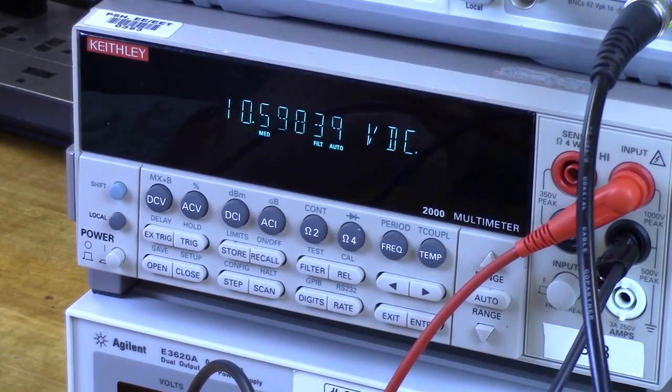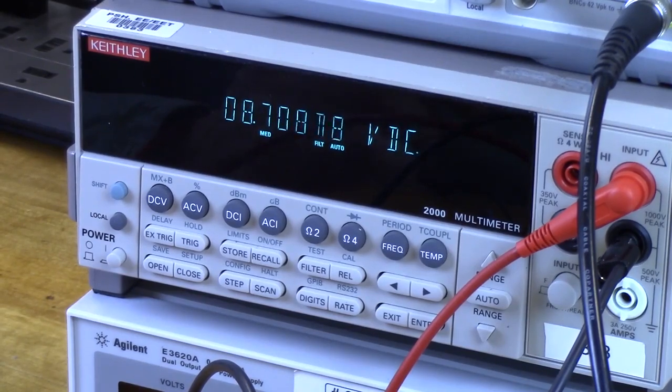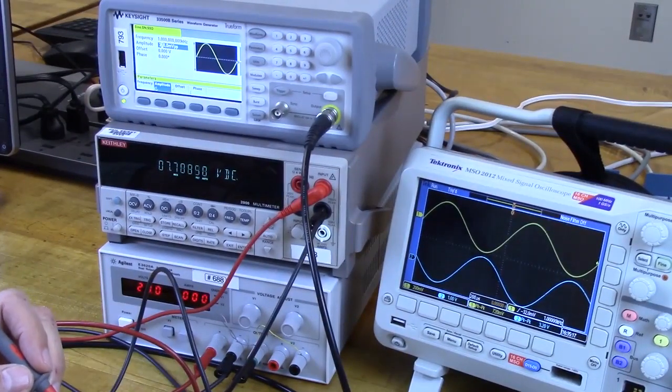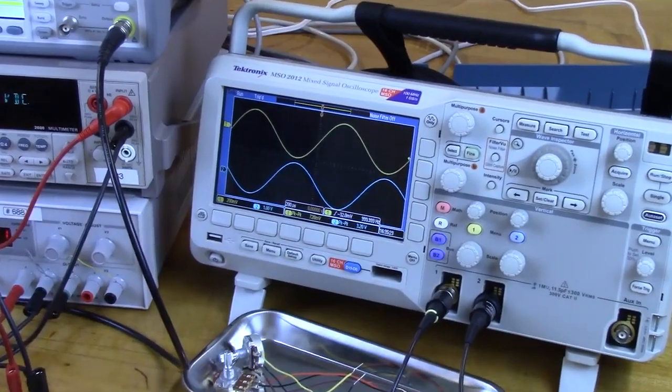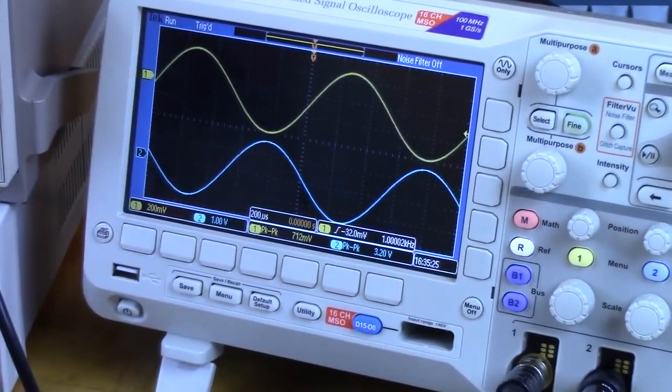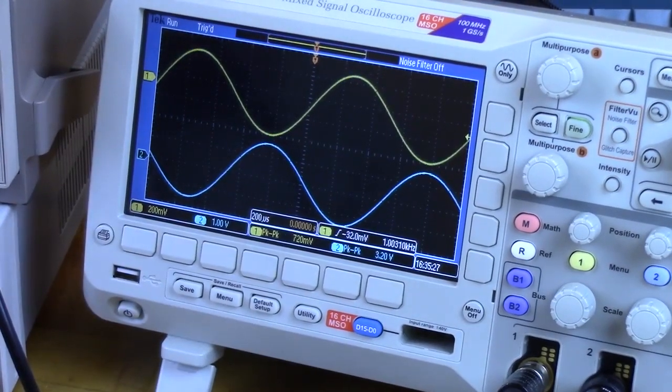And as you all know my philosophy on amplifiers, if the DC bias point is correct, you have a good foundation for your circuit, the AC will naturally follow. So let's start with our gain measurement. We have the input voltage here and the output voltage there. Let's be clever and measure that with a meter to get some precision.